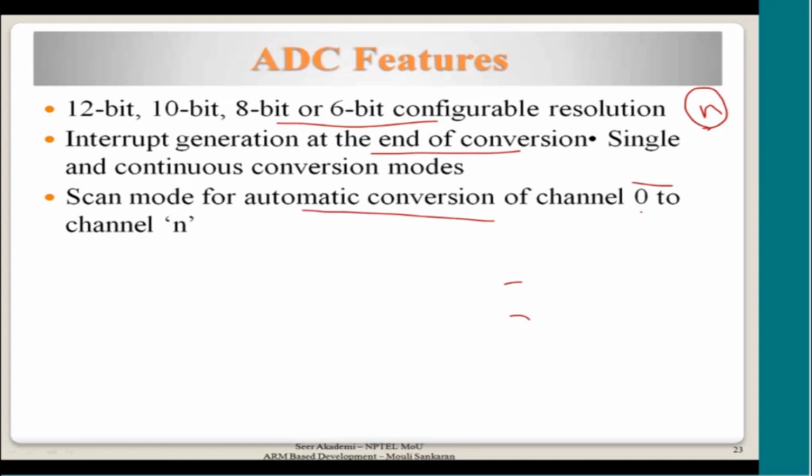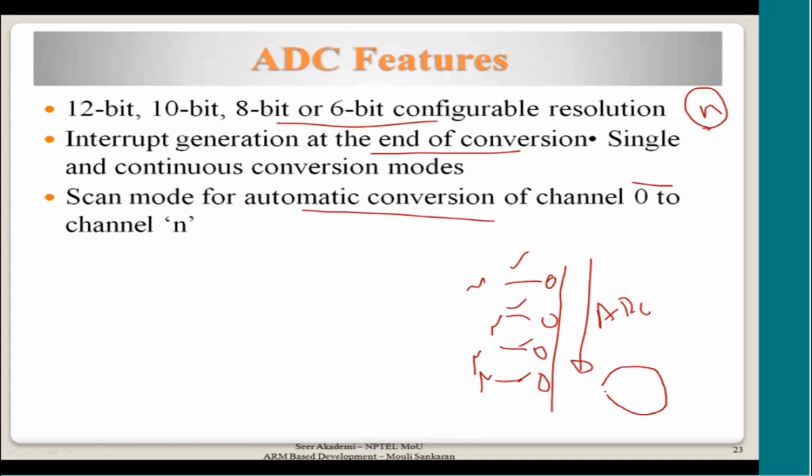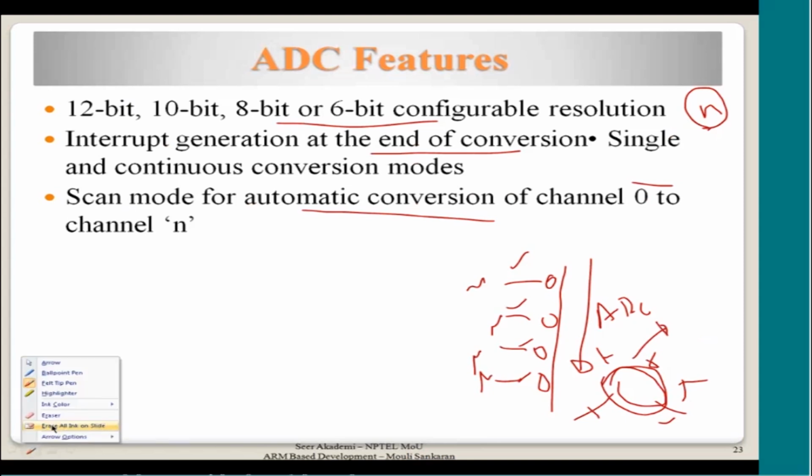So you may have multiple channels with analog signals, where various sensors are connected. Then the ADC will have multiple channels. It will be converting this first, and then the next, and the next. It can go in a particular order, sampling the values of different inputs. So periodically, if you want to sense different parameters, with all the sensors connected to the system, the ADC can be sampling all of them and getting the values and generating digital information about them.